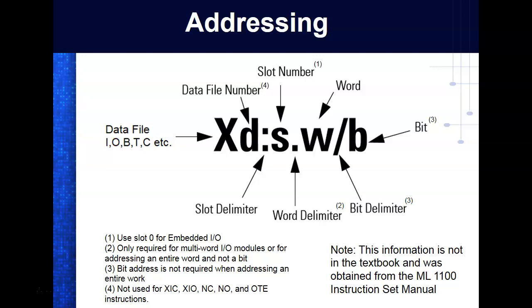So this is the actual book that goes with the Field Tree. This is not in your book. We'll be referencing that every once in a while too. Like I said, the guy is really good on the book, but he does have some problems. He misuses the word register. He'll draw a normally closed contact hooked up to the PLC, and then he'll use an examine if open instruction inside his program. That's one of the problems he has. Like I said, he calls elements registers, and we'll make sure y'all understand that.